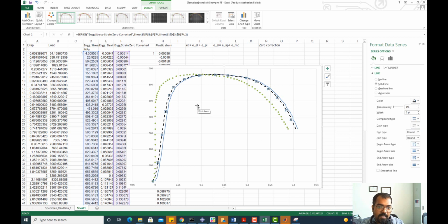and after shifting, after removing all the elastic strain, you see that the curve becomes straight, because the inclination in the stress strain curve is because of the elasticity, because the stiffness is not infinity. So once you remove the elastic part, it becomes straight. What does it mean? It means that any finite value of x-axis will start only when the yielding has started,